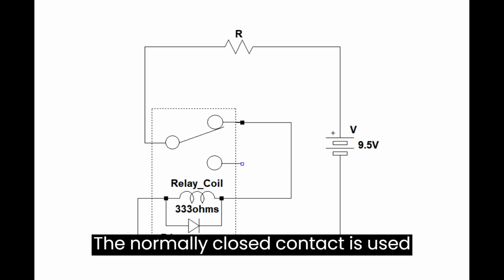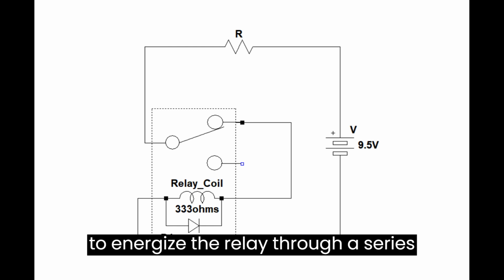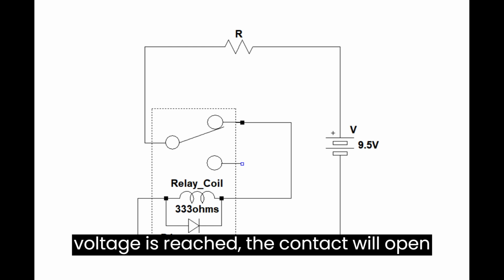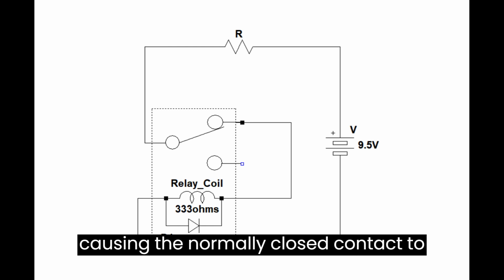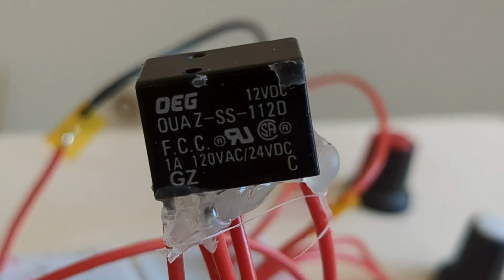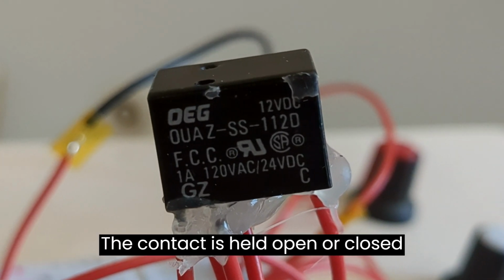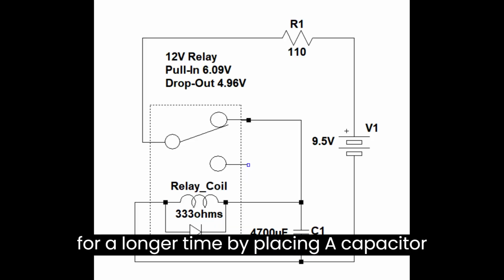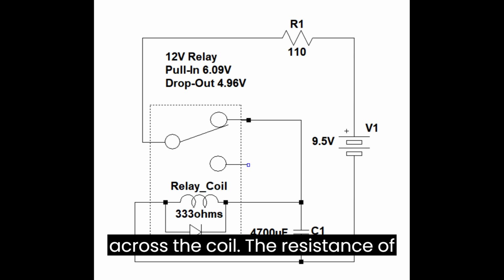The normally closed contact is used to energize the relay through a series resistor. When the pull-in voltage is reached, the contact will open, causing the normally closed contact to open. It operates like a buzzer. The contact is held open or closed for a longer time by placing a capacitor across the coil.